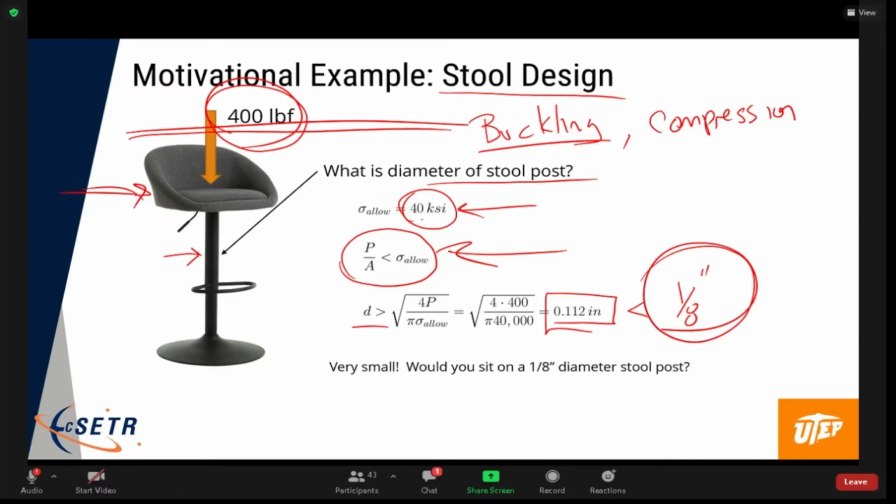But in fact, if I put a force on it, you can't tell, but I'm slightly increasing the force, and then that's buckling out of the page. And then it jumps down, right? So this is a buckling phenomenon. The post has buckled. Obviously, that term is from layman's parlance, and that's what it means, okay? But this is the issue that we're going to talk about here.